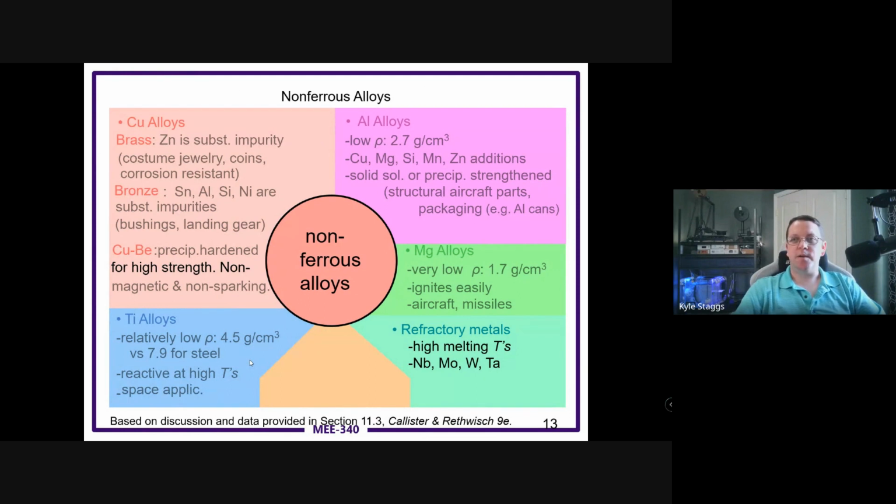Basically, what those are doing is using their extremely high melting temperatures, and depending on the alloy, they can also be very hard. So when possible, I tend to run tungsten nozzles, which are really, really awesome for printing.